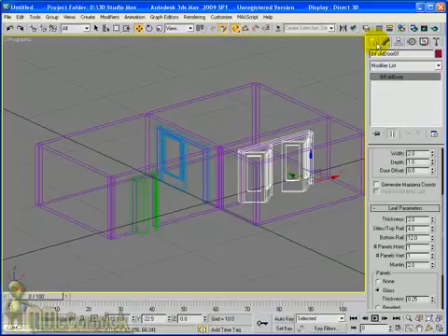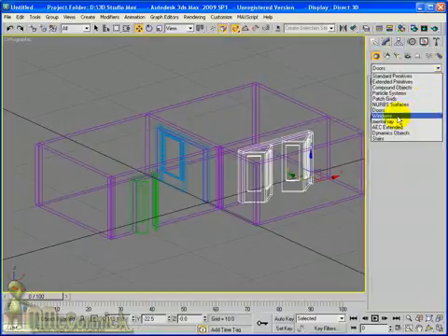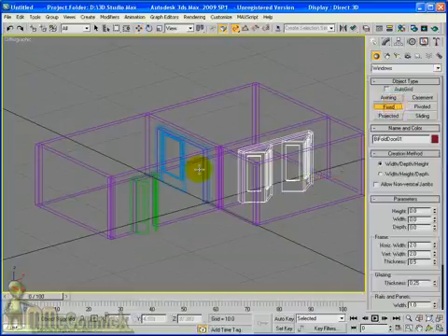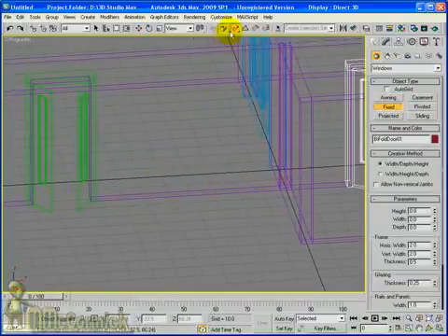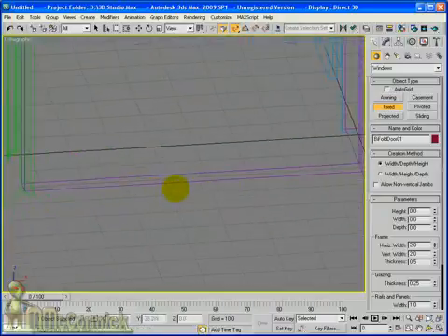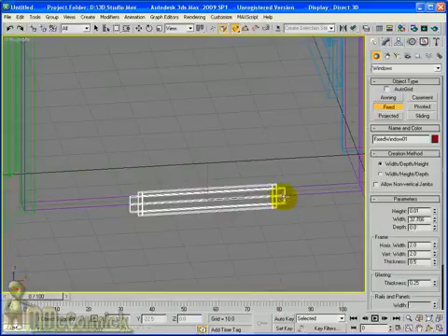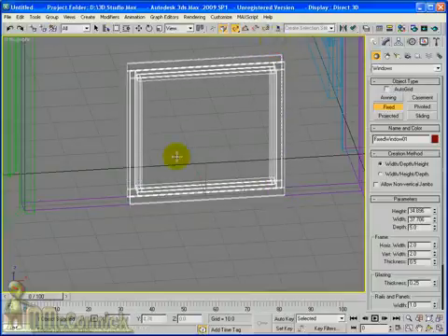So you have your pivot, sliding and bifold door. Now we want to add some windows, so clicking on the create panel, clicking on the drop down, and we select windows, and you can see there are 6 different types of windows. The fixed, the one that we're going to go for first, and this one is just a nice simple window to use. Again, make sure that your snap is on, right click and just check to make sure edge segment is enabled. I'm going to close that, and on the edge click, drag, define its thickness up and click.